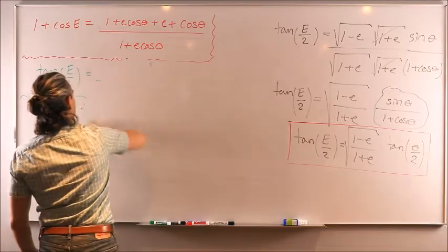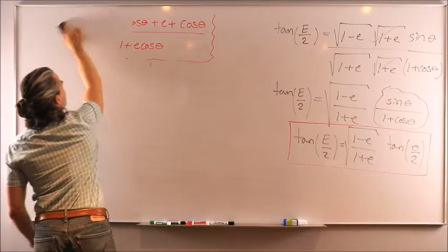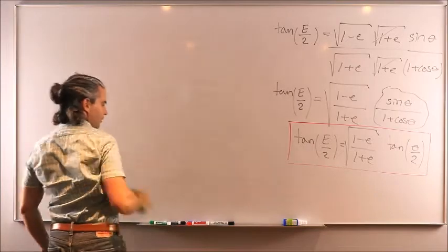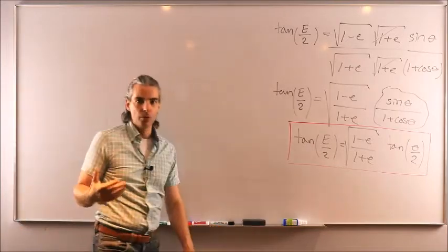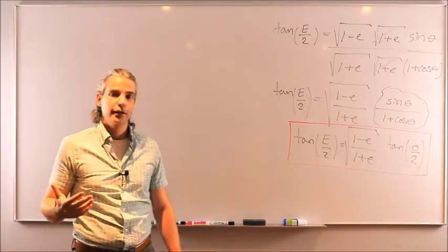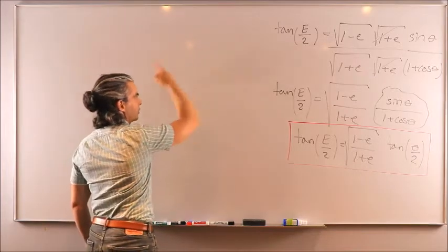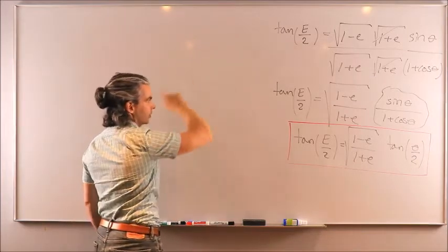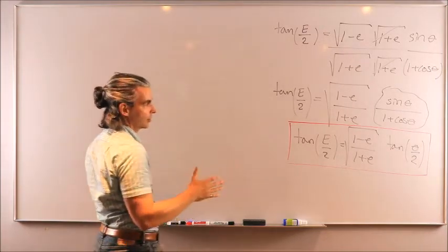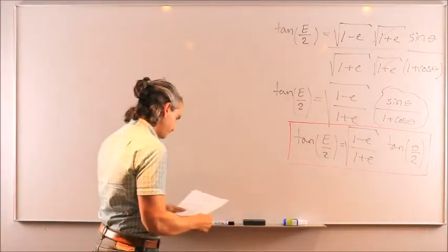So as you can tell, this is much more tedious than the circular orbit situation, where the relationship was quite straightforward, and the reason was that the mean orbital motion was directly related to the true anomaly rate of change, because the position vector sweeps the orbit at a constant angular rate for a circular orbit, but for an elliptical orbit, that's not the case anymore. So that's why we have to go through these multiple extra steps here.